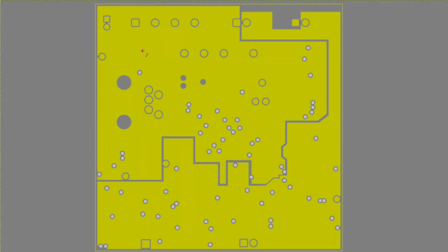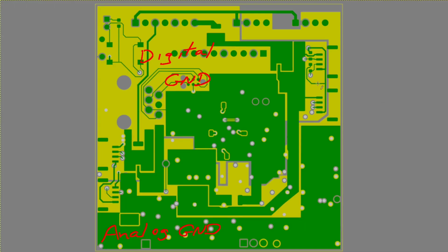I did try to separate the digital and analog ground planes. This being the digital area, with the closest connection to the power grounds coming to the board. And then this ground plane is where all the analog parts ground to. The path that connects the two planes is this one large trace. It starts right at the ground terminal of the 3.3 volt linear regulator and ties to the analog plane right at these 4 vias. All the previous waveforms were referenced to digital ground.